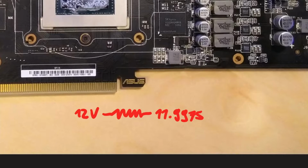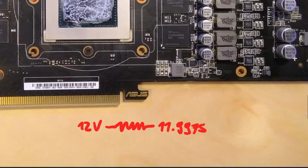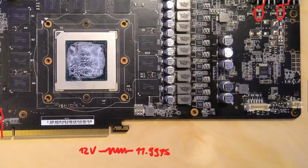And since that's a resistor there, and resistors do drop voltage, you lose a very, very slight amount of voltage, because, well, it's just 5 milliohms, that's not a lot of resistance, it's very little, actually. So, yeah, instead of 12 volts, you might get 11.9975 volts. And the INA3221 measures both of these voltages, and then compares them.